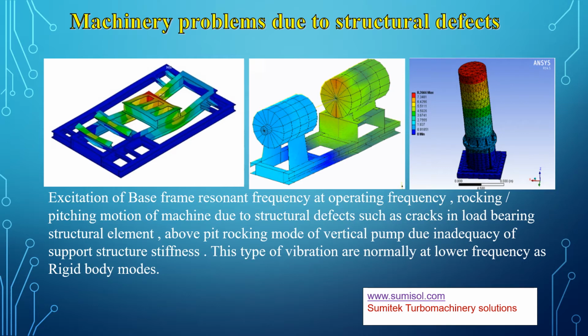Often we have observed that routine problems on machines, especially those pertaining to unwanted vibrations, may not only be attributed to rotating shafts or bearing designs or other operational anomalies, but also majorly tend to occur due to structural defects on the equipment. These structural defects may be present from the beginning, say due to poor base frame design, or may develop over time. Either way, these anomalies can persist with lower frequency vibrations having an adverse effect on machine life.